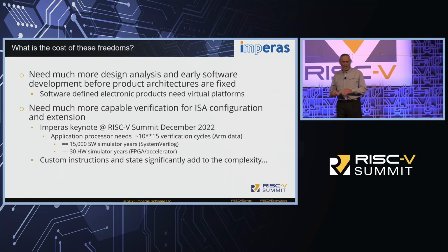The second thing is you need much better verification technologies. I talked last year, actually, I don't think it was on this stage, but at the summit, about the challenges that people have in verification. And I quoted some data from ARM, where they do 10 to the 15 cycles of verification on a high-end processor. On the state-of-the-art SystemVerilog simulators, that's 15,000 years, if you go through the numbers, or 30 years on an accelerated FPGA. And that sounds a lot, but actually, if somebody's doing a big chip, it takes about 2 years of verification with a lot of hardware assist. So it's very important to do a lot of verification to get the quality up.